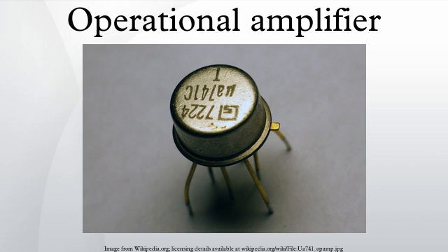This setup uses a normal op-amp with an additional AC amplifier that goes alongside the op-amp. The chopper gets an AC signal from DC by switching between the DC voltage and ground at a fast rate. This signal is then amplified, rectified, filtered and fed into the op-amp's non-inverting input. This vastly improved the gain of the op-amp while significantly reducing the output drift and DC offset.